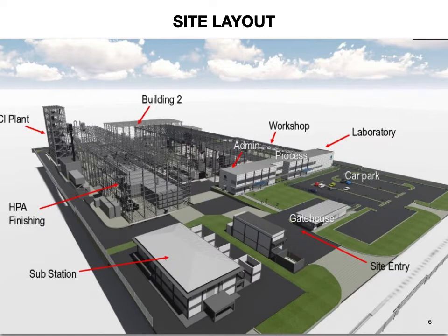The initial layout is usually based on the processing units being positioned relative to one another based on the process flow diagram. However, I might tell you now, your PFD does not show scale or structure, but only provides a widely understood representation, in a simplified format, of a plant's unit operations and process flow.